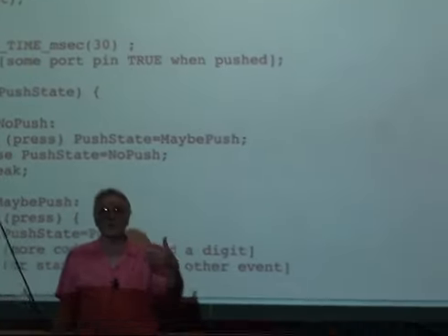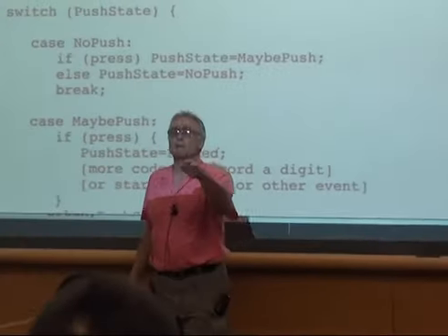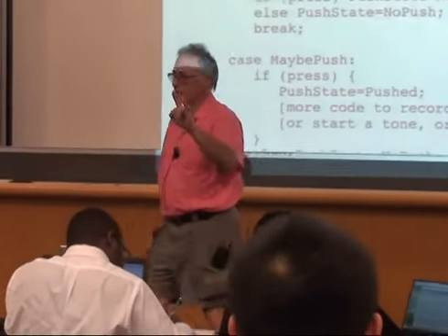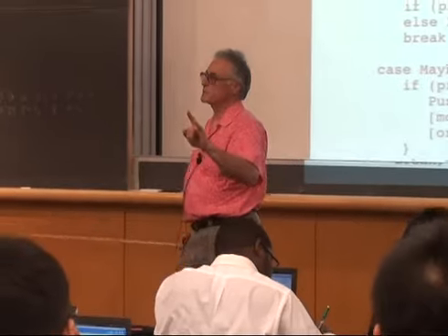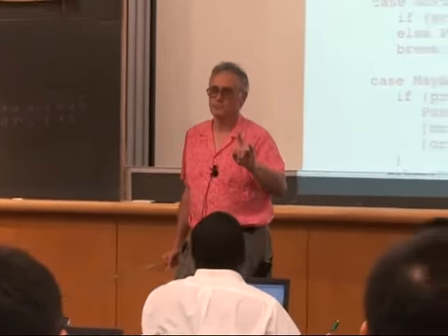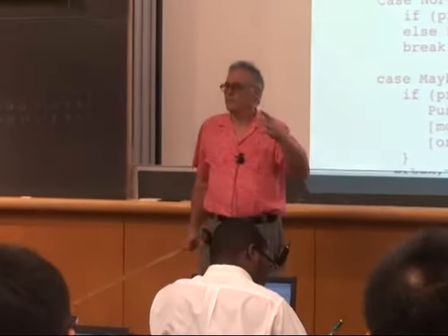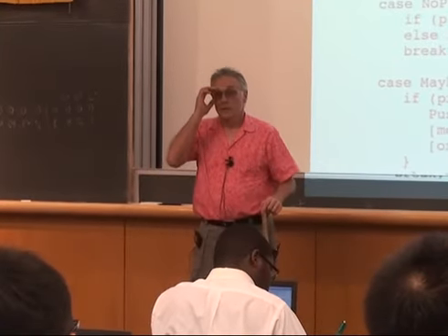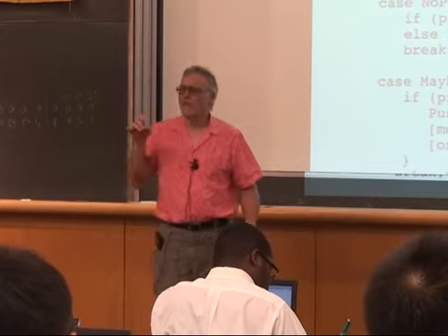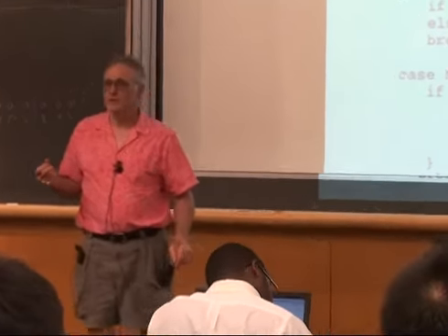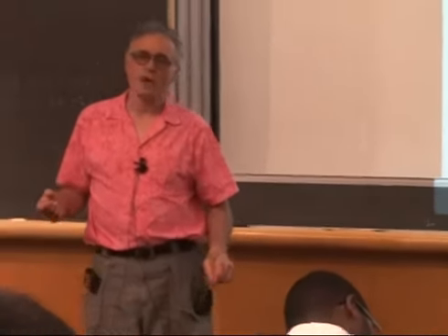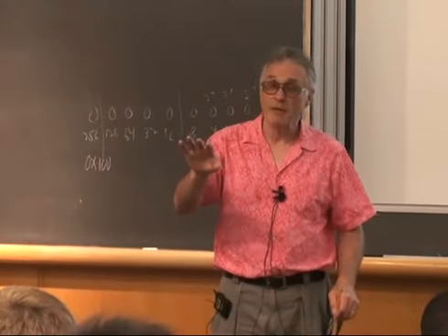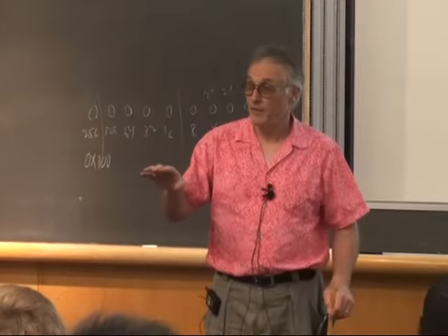That way it will have a fresh push button state every time through the state machine, which will happen about every 30 milliseconds. It's about right for humans. You could tune it. You could make it a little slower, a little faster. If you find that 60 milliseconds feels laggy, you could drop it to 20 milliseconds or 15 milliseconds. But don't drop it much below 10 milliseconds because you'll start getting into the bounce regime of the keypad itself.